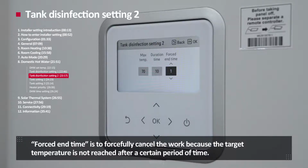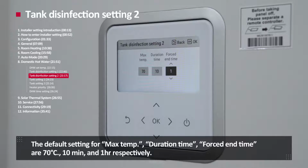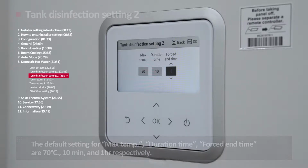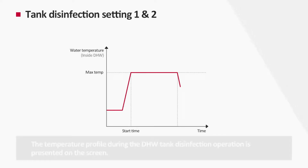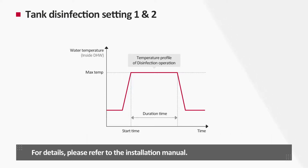Forced end time is to forcefully cancel the work because the target temperature is not reached after a certain period of time. This time can be set between 1 and 12 hours. The default setting for maximum temperature, duration time, forced end time are 70 degrees Celsius, 10 minutes, and 1 hour respectively. The temperature profile during the DHW tank disinfection operation is presented on the screen. For details, please refer to the installation manual.